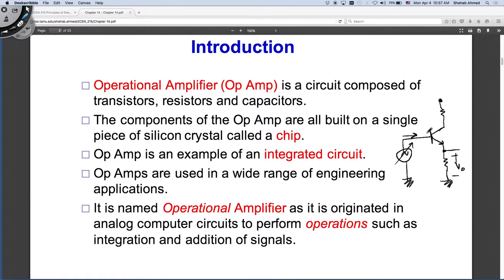So you may be measuring flow, and they will tell you that the output is 4 to 20 milliamps. This is very typical of a sensor used in process instrumentation. It can give 4 to 20 milliamps, or 0 to 1.8 volts, or 0 to 5 volts, or 0 to 3 volts, etc.